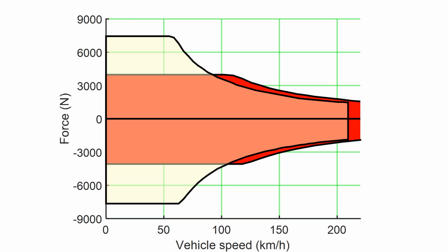For an electric machine which can keep the power constant at high speeds, an additional gear will not increase the force. There may however be other reasons to use 2 or more gears. A second gear may be needed if it's difficult to simultaneously meet the low-speed force requirement and be able to reach the top speed with the same gear ratio.